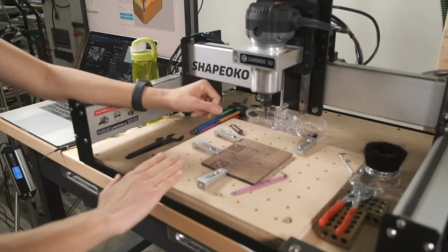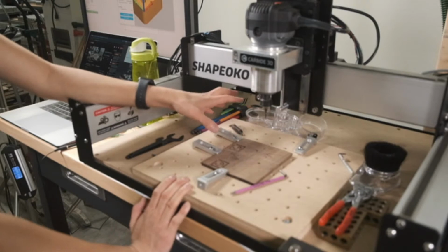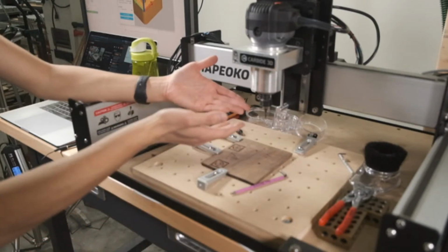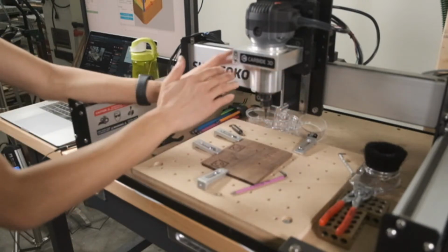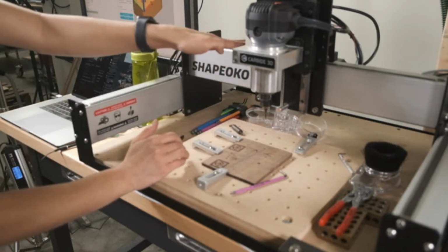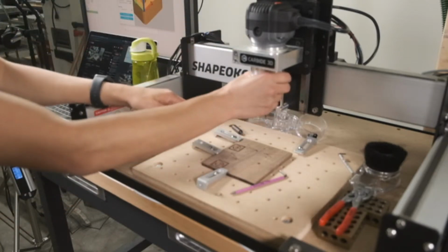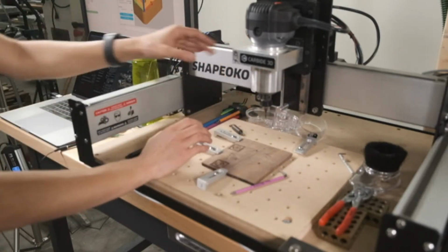So that's why I like to keep a supplementary wasteboard on top, just to elevate the piece a little. I can move the spindle up in the mount a little bit, and that actually reduces the tendency for this to want to buck or bob or twist about the X rail.